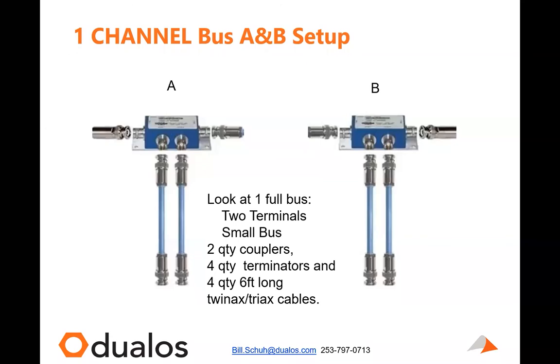I have seen transceivers get burned out because of some bounce that was seen on the wire. It was a lot worse of a connection than just a direct connection. So really the terminators help take that ripple out of the top of the waveform. And also it knocks it down by 1/3 of the voltage.